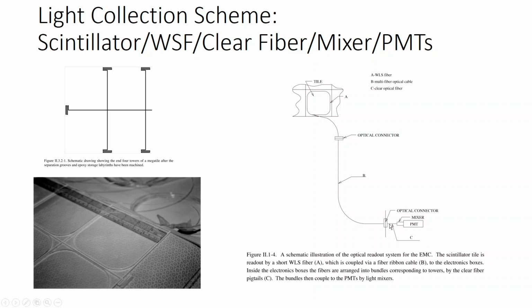One final signal conditioning is required. It might happen that the photomultiplier tube has areas of low efficiency and high efficiency on the face, and these could accidentally match with positioning of low and high light production from the bundle of 20 fibers. To make the photomultiplier tube response more uniform, we insert a rectangular prism which mixes the light from all 20 fibers in a random way before detection in the photomultiplier tube. This compensates for imperfections in construction and light collection and PMT efficiency variations.